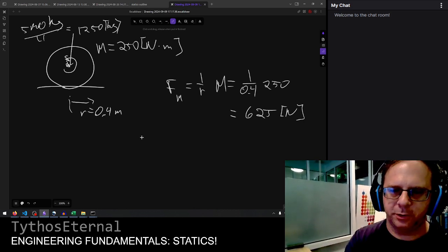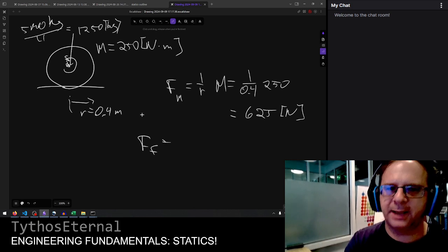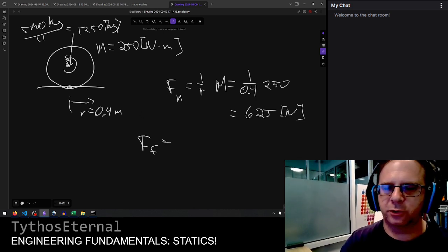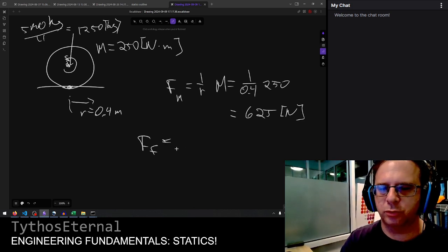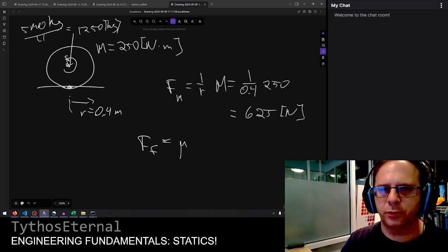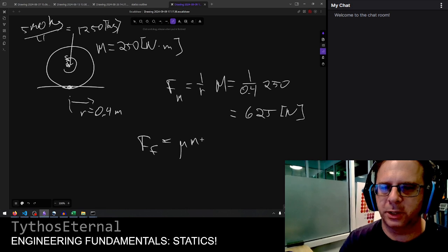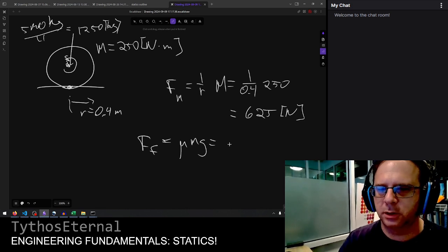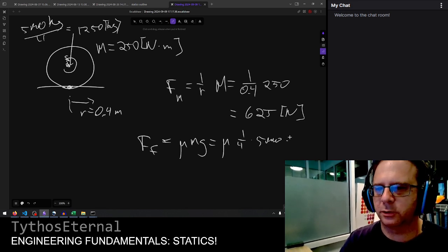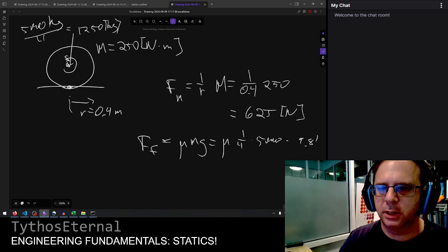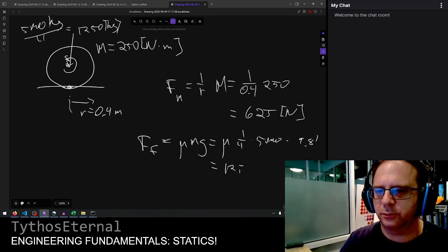And then we know the frictional force at that boundary is going to be a product of the normal, right? So the normal force in this case, we're purely vertical, so it's just the mass times gravity. So there's some mu. It's a quarter of 5,000 times 9.81, and that comes out to 12,300 times mu.